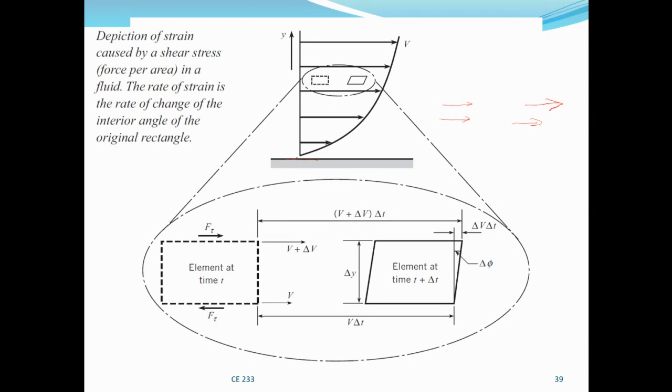And that is because of the viscosity, because the lower boundary is not moving. So the particles try to attain the velocity of that lower boundary, which is zero. Then they drag the layers above them, which have velocity. They drag them, and that's why the velocity increases up to the surface, where it is highest, if the surface is not bounded by any other plate.